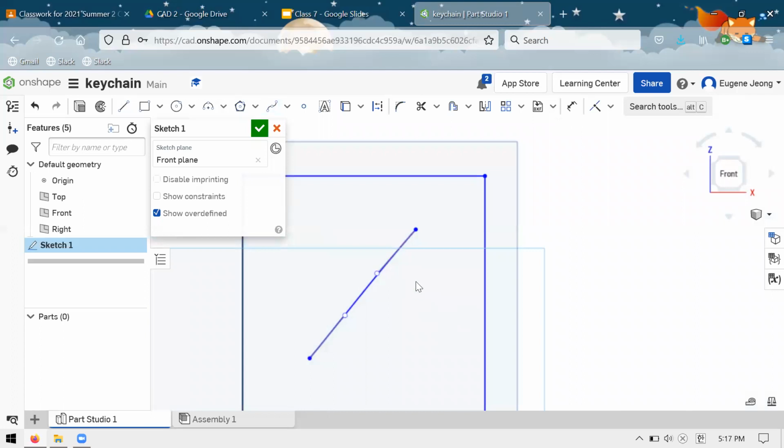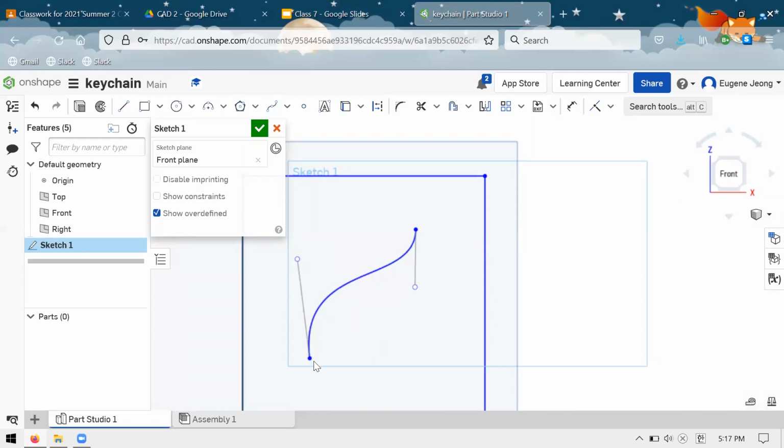what they allow you to do is drag them, and they indicate the tangent direction at the point where the spline ends. So here you can see that I can create some curves which are not circular with the adjustment of these two spline guides.